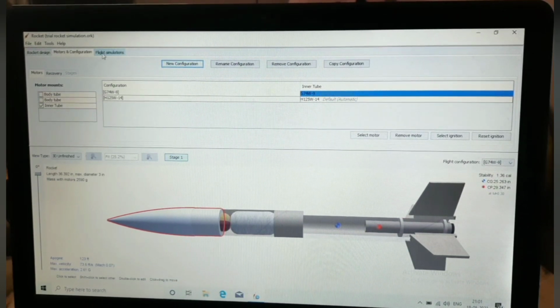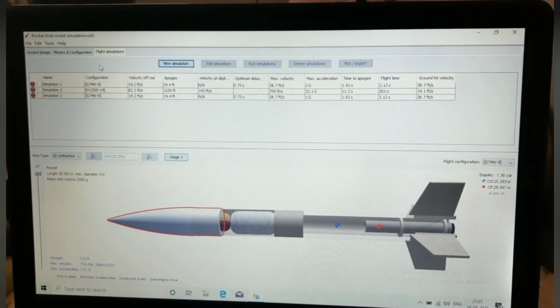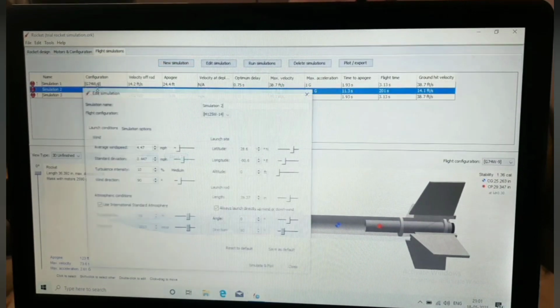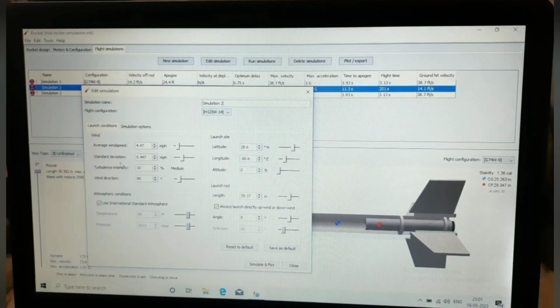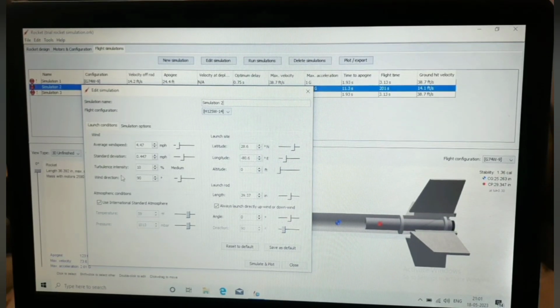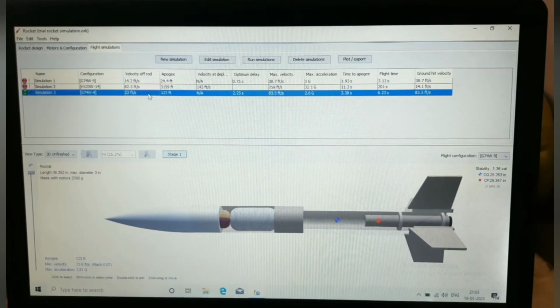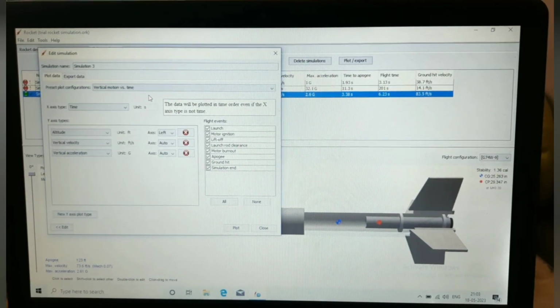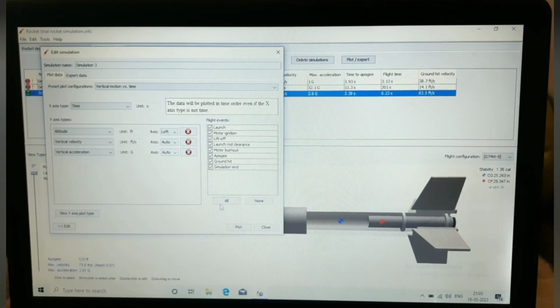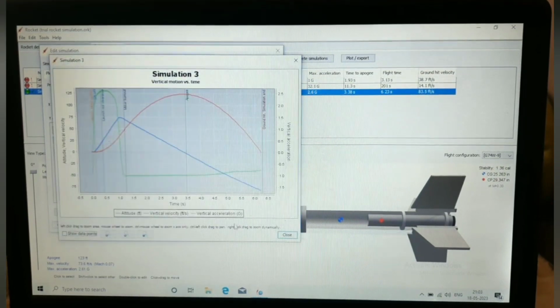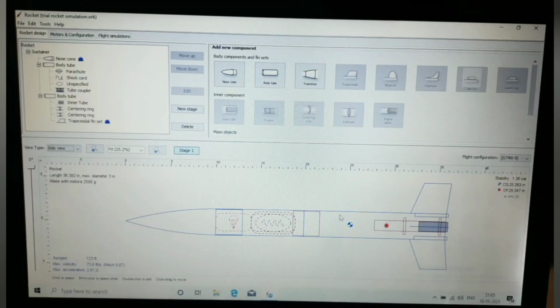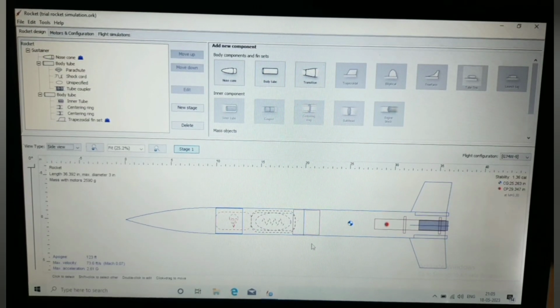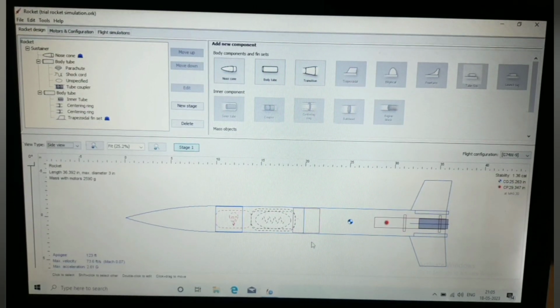Once the simulation is set up, we can adjust the environmental conditions like wind speed, standard deviation, turbulence intensity, wind direction, etc. The software simulates the flight and gives results according to the parameters we give as input. It also plots the graph of the flight. We can change the center of gravity by adjusting parameters. We can simulate multiple times until we get the desired output.